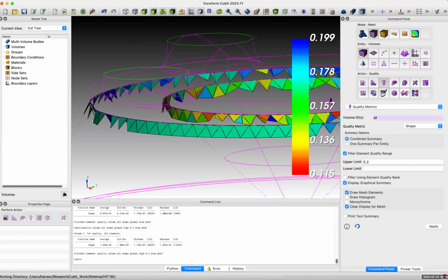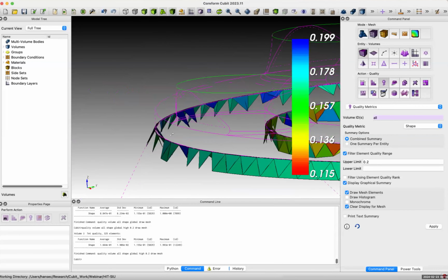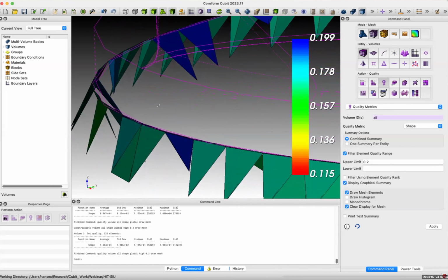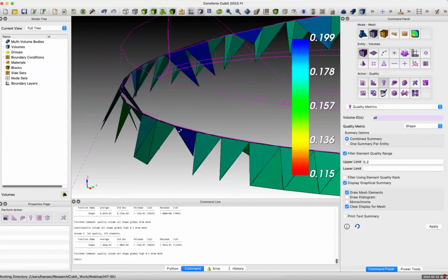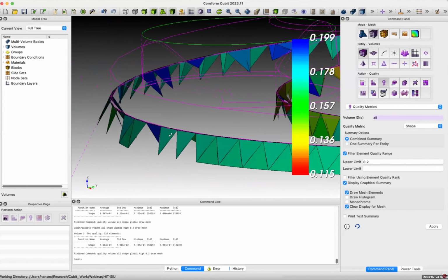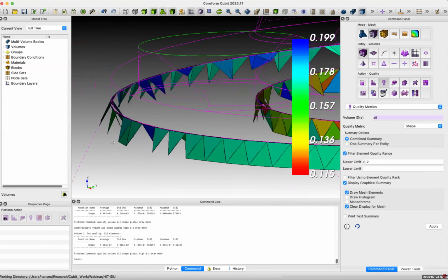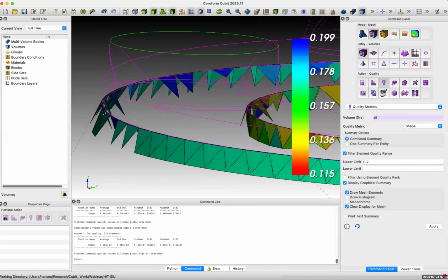You can see they're on the edges of the interface from the manifold down into the main volume. I didn't show these steps, but it turns out that when I fixed up the geometry, we ended up with a tiny little shelf surface here. You didn't really see that in any of the other cases, but what it does is produce a ton of these really thin sheet-like tets at the edge because they have this tiny narrow base up here.